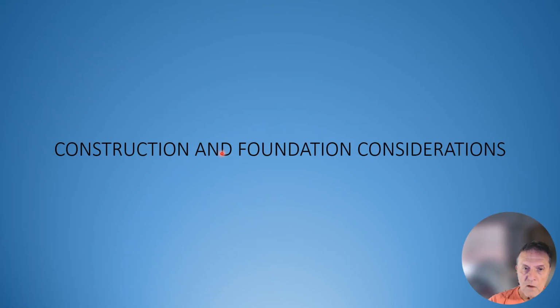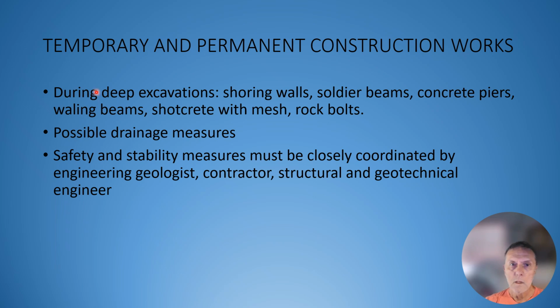Let's get down to practical considerations for construction and foundations. So you have excavations. You may have deep excavations. If you have deep excavations, let's say 30, 40 feet, such as an underground garage below a skyscraper, you might have shoring walls. You might have soldier beams, which are tied together by shoring walls.